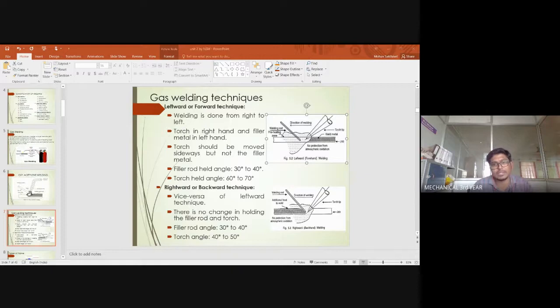You can see here the solidified fused flux covering the area of the weld. You can see some dots over here which represent your unused flux. This is called unfused flux. This can be sucked back with the help of your vacuum.